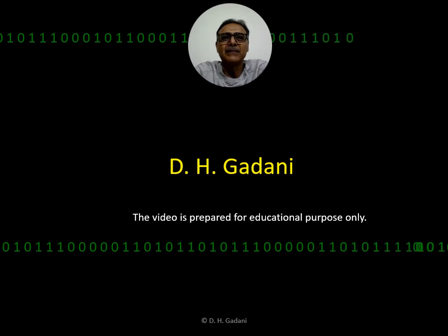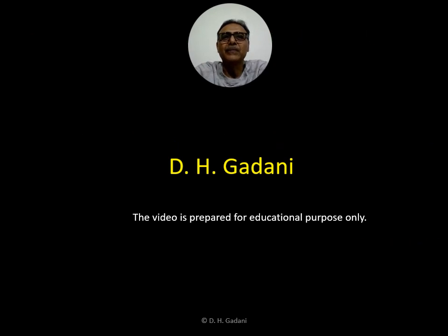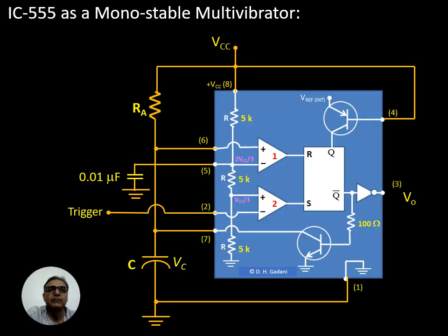Today, we will discuss the use of IC555 as a monostable multivibrator. As you can see, the three resistors of 5 kilo ohm each are connected between VCC and ground. So, the voltage across each resistor is VCC by 3.